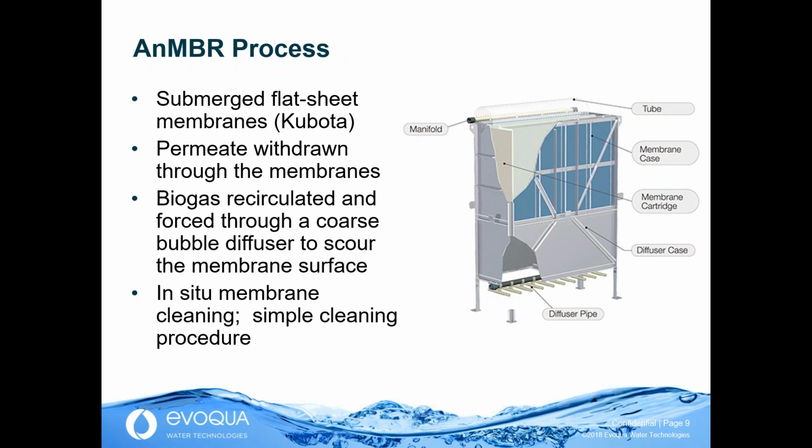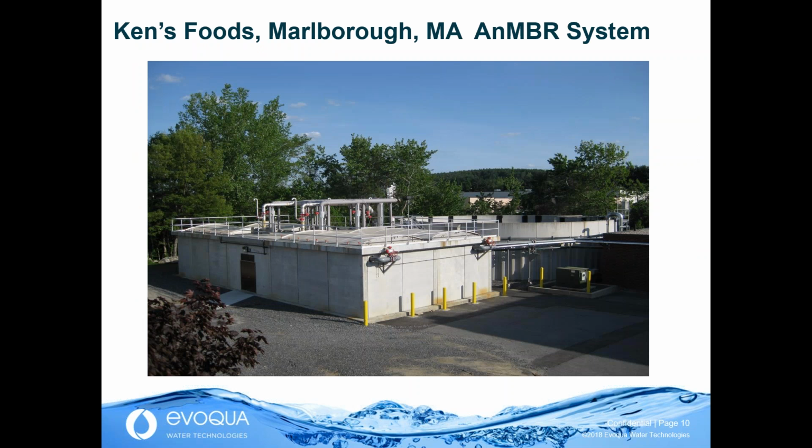Now I'm going to switch gears. I'm going to go through some of the systems that we have and talk about how they work, why the anaerobic MBR is there, and how it works. The first system I'm going to talk about are the anaerobic MBRs installed for Ken's Foods. Ken's is the leading producer of barbecue sauce and salad dressings, and the wastewater from these plants contains high concentrations of COD, TSS, and fat, oil, and grease, which makes them a good candidate for treatment with anaerobic MBR.